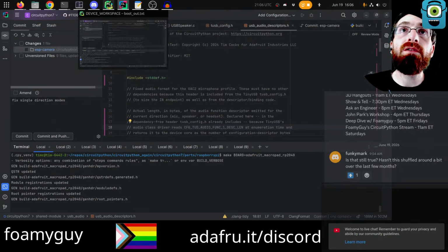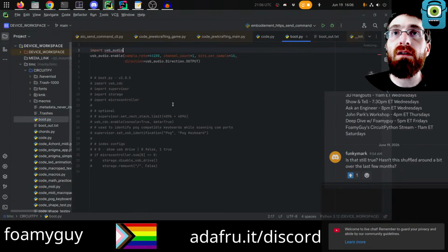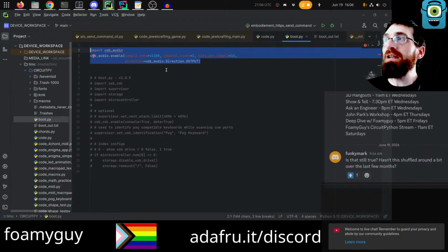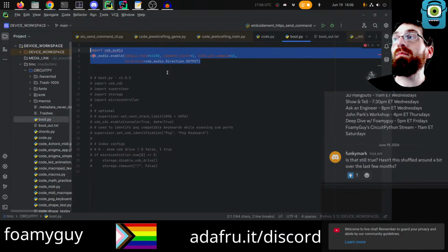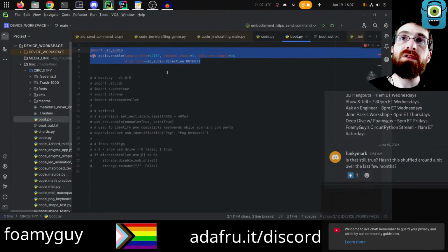While that's running, I can show you the start of what this one does. I'll run through it from where you have to start. Because this is a new USB endpoint, it's connecting as a new kind of USB device. One caveat is there are a limited number of USB endpoints available. Some are used for HID, some for MIDI, some for storage, some for serial. Some of these are already in use, and there are a limited number of them.